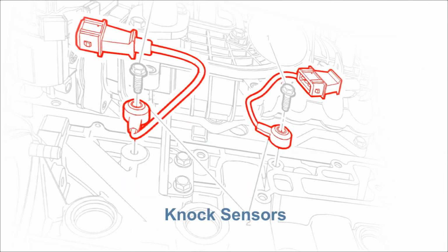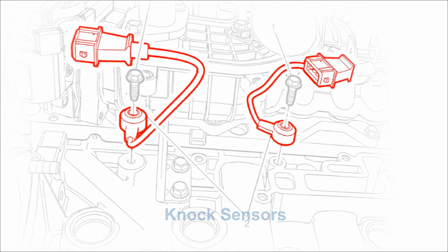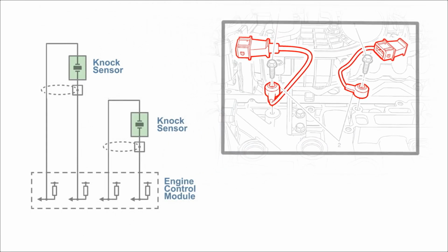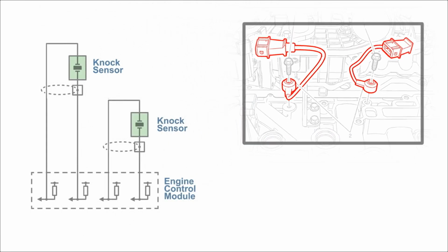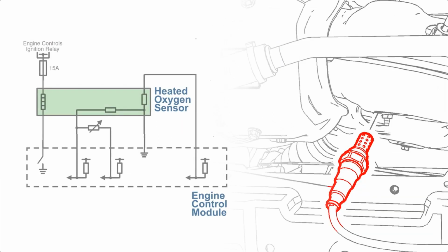2 NOx sensors are fitted to this engine. They're used to help the engine idle quieter. When the NOx threshold is reached, the ECM will adjust the pilot injection at idle in an attempt to reduce the noise. A wideband oxygen sensor is provided on this engine to assist in the reduction of emissions.